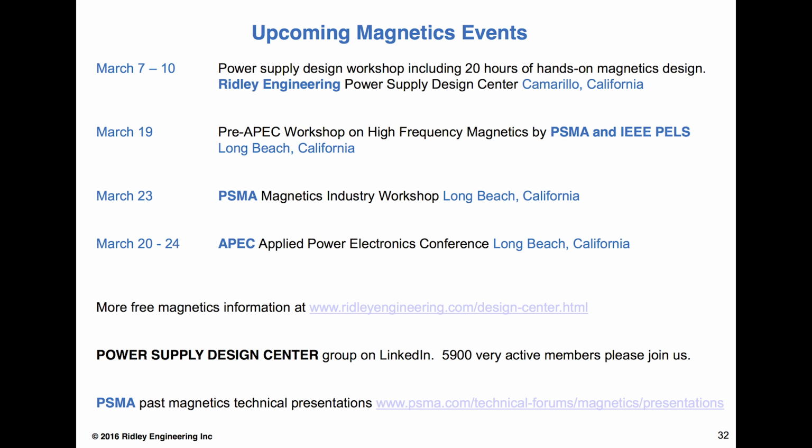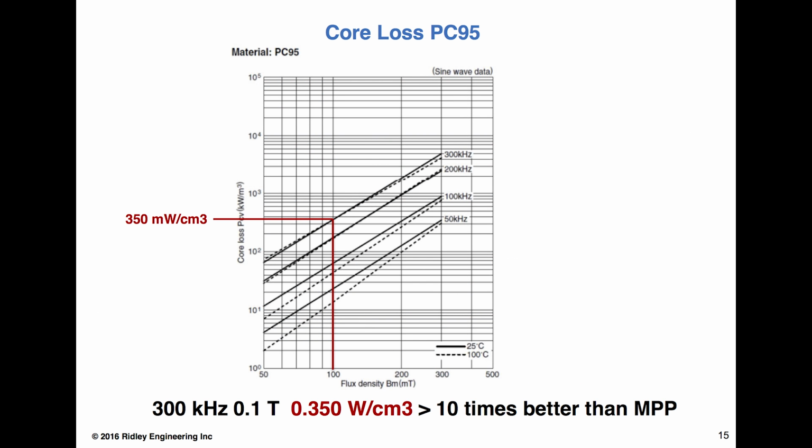First one is talking about the saturation levels versus the B at which the core losses are measured. So why do we accept a standard SAT level for ferrite as 300 millitesla, but you show core loss examples in your presentation taken at 100 millitesla? I believe the slide was 21. It was probably 15, I think.